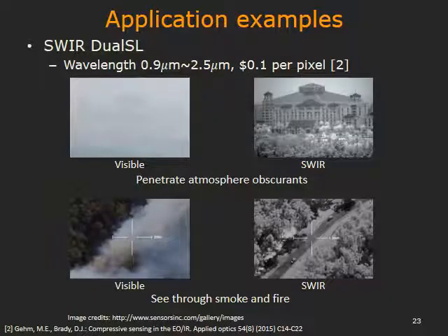We conclude by highlighting applications of dual structured light. Imaging in shortwave infrared is one such compelling application. Sensors in shortwave infrared are prohibitively expensive. Here, a low resolution line sensor can offer tremendous reduction in the cost of the imaging system, without any loss in the resolution of the obtained depth maps.